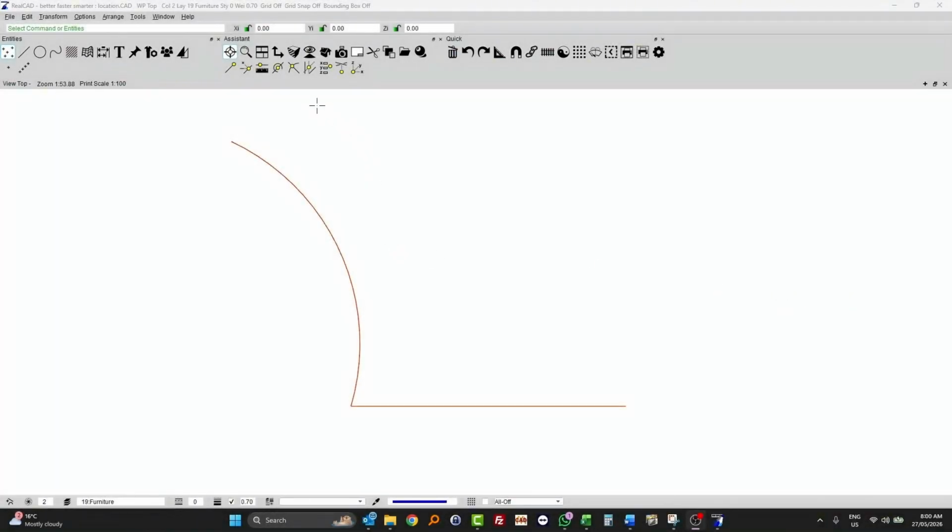In this example, we're going to look at the offset tool. We're basically looking at offsetting from two other objects. It doesn't have to be two, but there's certainly a use case where it's very common that we would use that. So what I might do is draw a circle, with a diameter of 1 meter, and select OK. I'm about to position this circle somewhere. Let's say that this represents a hole or a tree, and I need to locate it relative to maybe the fence line here and the curb of the road here, in a cul-de-sac.